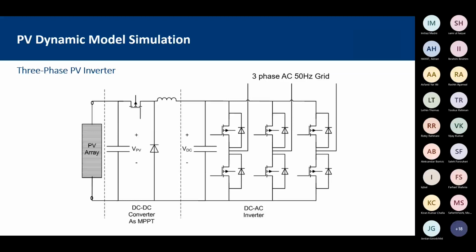That's another thing where PSCAD is, I think, very useful. PSCAD allows for analysis of unbalanced faults as well, like single line to ground or line to line to ground faults, which distinguishes PSCAD from other similar software. PSSE is also very useful software, but it lacks that feature. So that's where PSCAD is mostly used for dynamic studies.